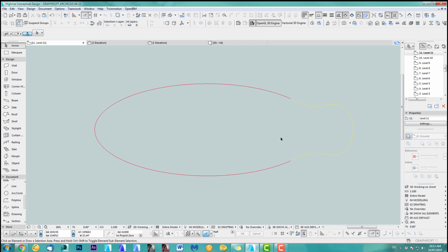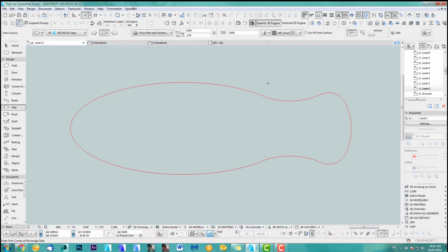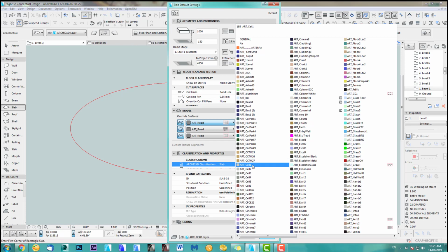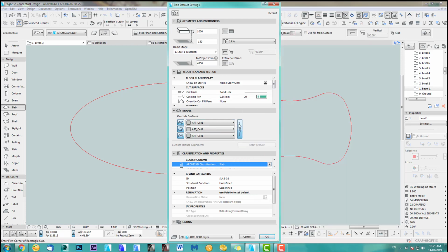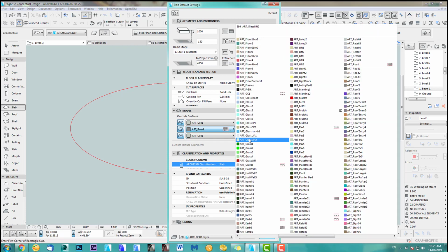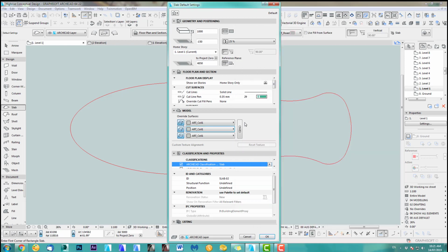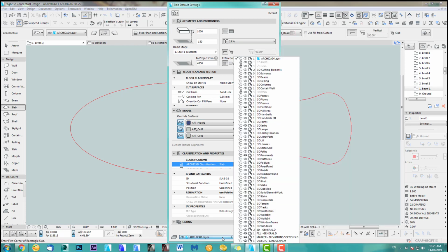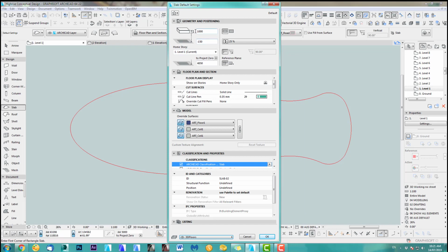So the next step is I like to add a slab. So we go in here, and I like the material to be a ceiling material at the bottom. So it's all ceiling. Hang on. Ceiling at the bottom. There we go. Ceiling at the side for now will do. And at the top we could add a floor. Let's do floor number 1. And we put this on a layer called floors. All right, make it 1 meter thick, 0 to the current ground floor level, and then we go okay.